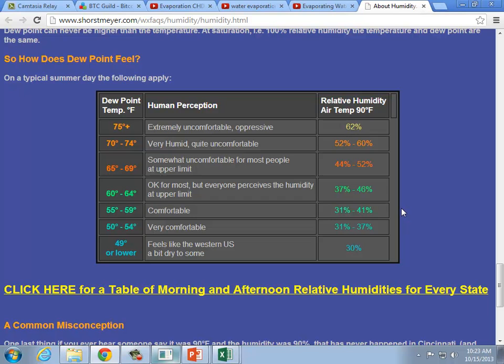But when it's windy, the boundary layer, that part of the air that is warm around my hand, is much thinner. And so the heat can move a lot more quickly between my hand and the air next to the hand when the temperature gradient is a lot different. When there's a big difference between the air temperature and the hand temperature, then heat transfer is quick. But when there's a small difference, there's a very slow movement of heat from one object to the other. So that's sort of why wind chill is accounted for during the wintertime.